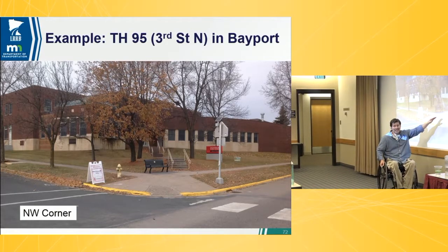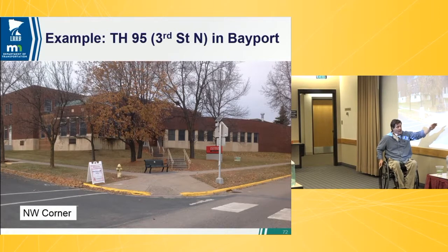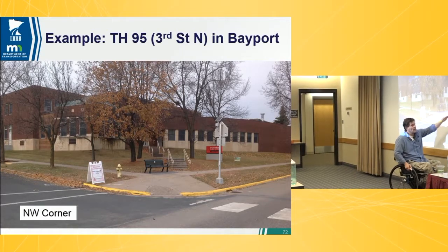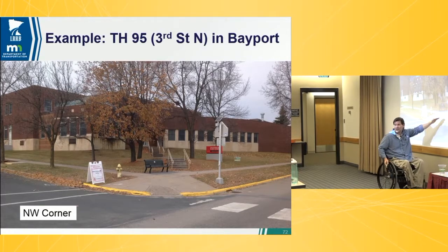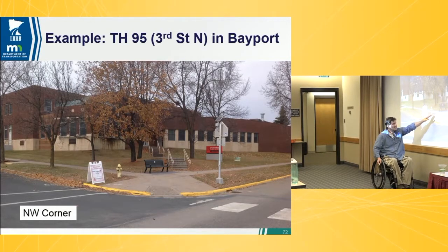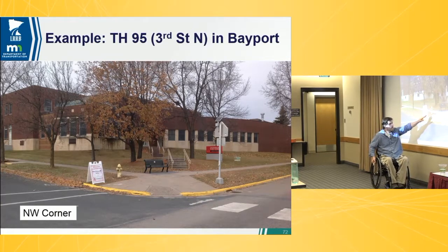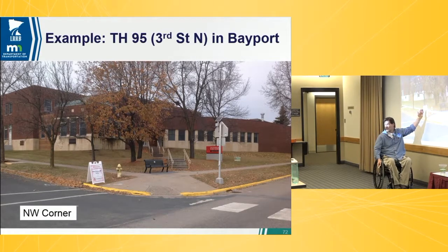I'm going to drop this down a foot, modify the railing, and I'm going to chase the sidewalk out this way. I'm also going to chase it back this way, but I'm going to lower this landing a foot. So for example, to chase this out, this is a 3% slope. If I want it to be a 5% slope, I got to chase 50 feet back. If I want it to be an 8% slope, I got to chase 30 feet back, whatever works. But again, I'm lowering that a foot. So I still got 8 inches to come out of this thing.